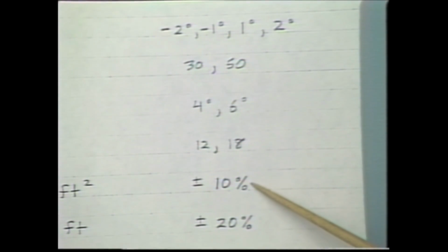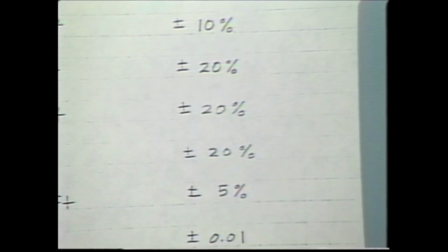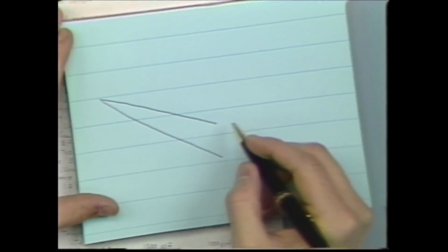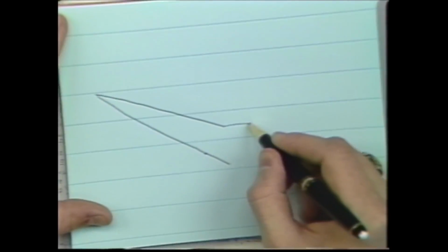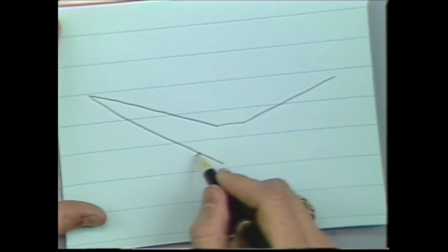The capture area, that's just basically the height of the cowl. And I tried to do these in such a way that everything else was separate. These were independent variations. So the capture area was actually varied by, let's say that's our forebody, and there's our shock. You can change the capture area for a given length vehicle, say it's that long, by just sliding up and down the shock.